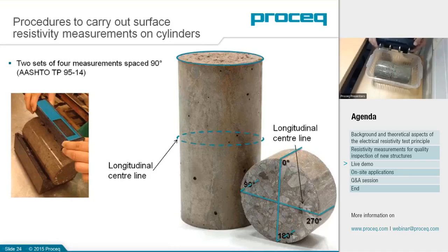It has 4 spring-loaded probes. So now it's easy, but even, and still going to answer some of the questions, it adapts even on irregular surfaces. What we see while measuring, is it readable? Yes, that's perfect. Okay, I need my pen. Okay, here we have a direct indication of the resistivity in kiloohm centimeter.